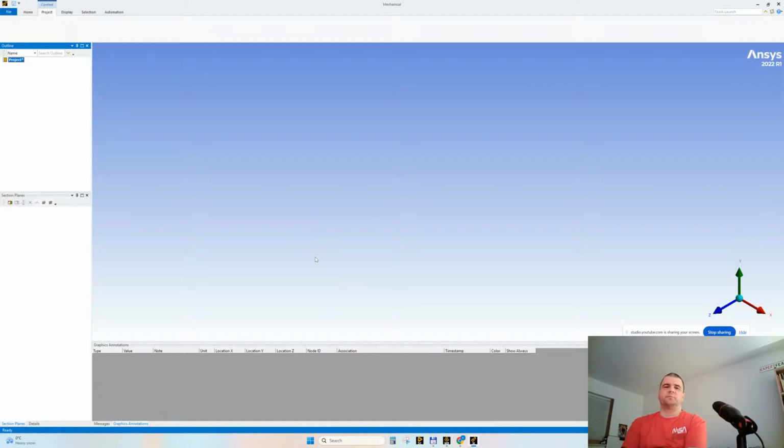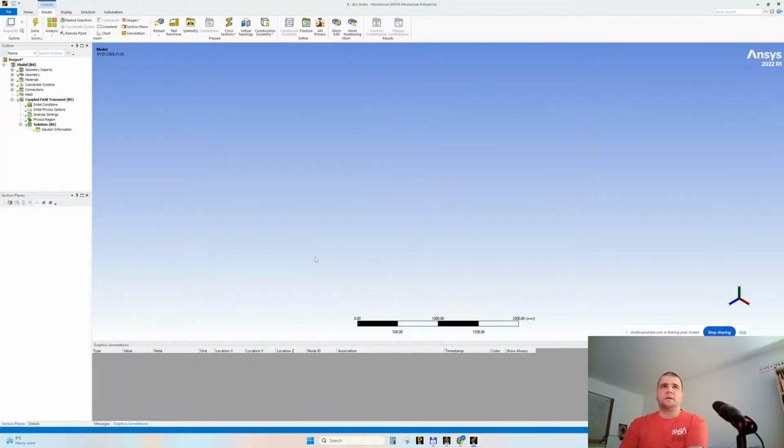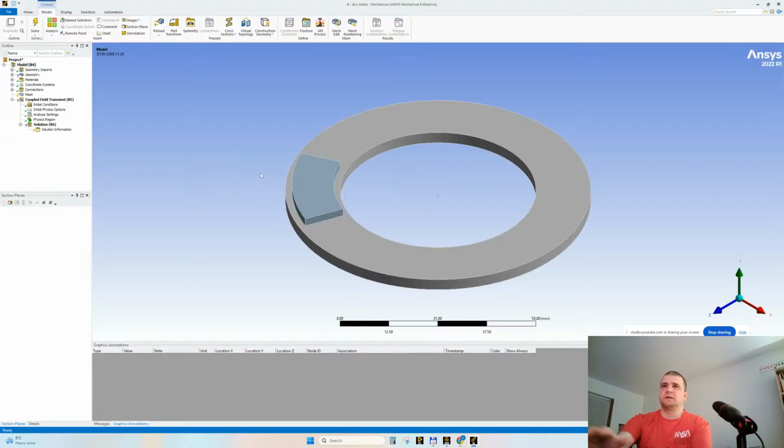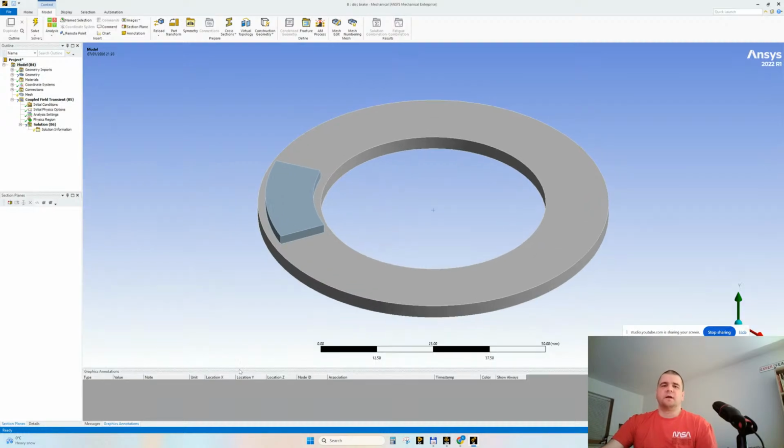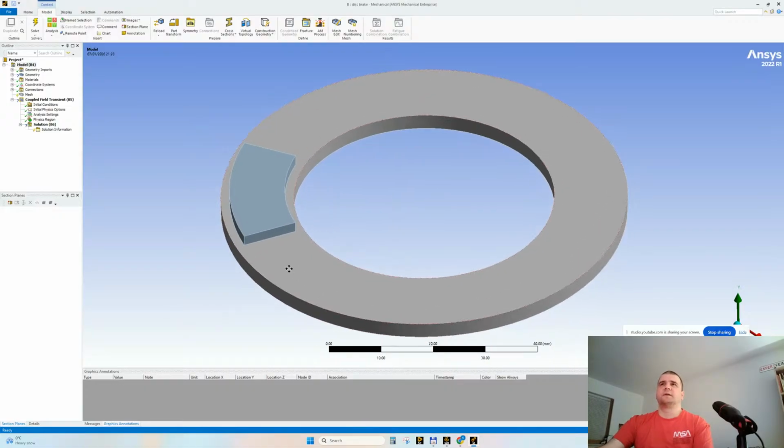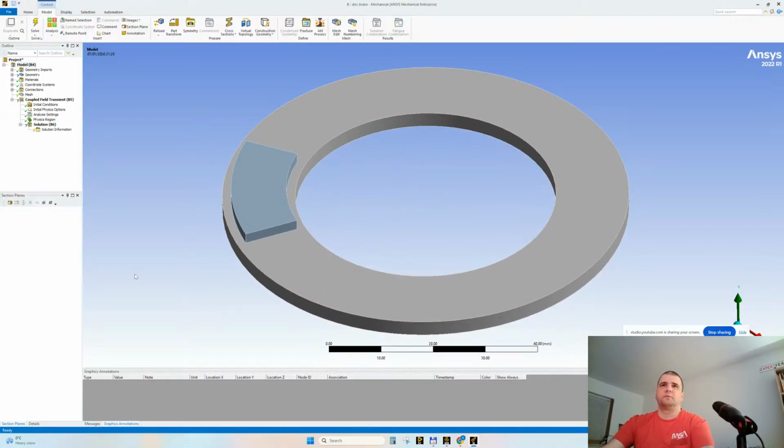Normally, we need to have the proper geometry, the proper gap, the proper tolerances, let's say. Then we need to have a fine mesh with high quality. This is why sometimes the FEA stops and does not converge. Because what I'm doing live is mostly improvisation, and it can go so far, yes. Normally, any FEA topic should be studied for at least a few days or weeks.